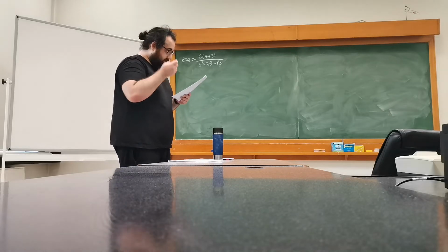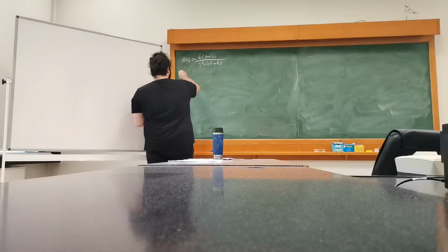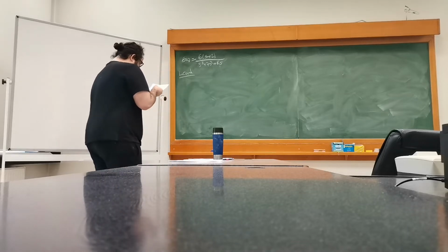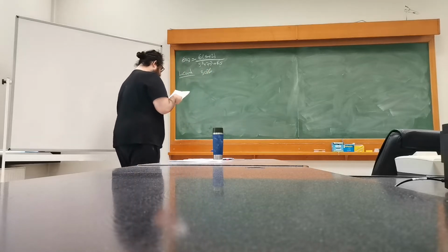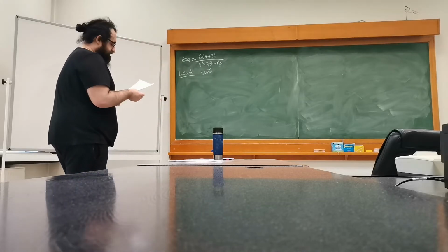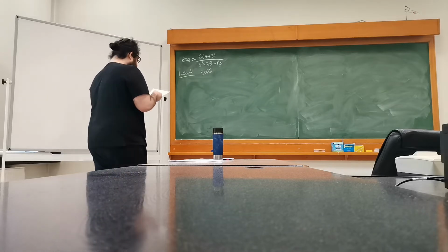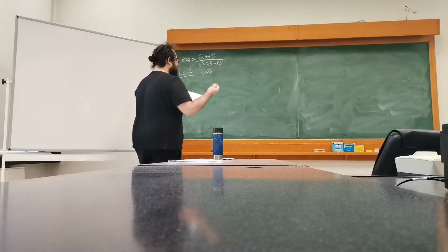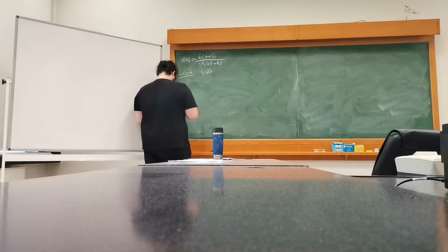Okay, now we have designed a lag controller in Q3. Now in Q4, we're looking for a lead controller design. And again, we have the same overshoot value, 30%. The only difference from the previous system is that we have a zero at s plus 2. So in order to design a lead controller, we are again going to use the frequency domain, and then we'll talk about the time domain.